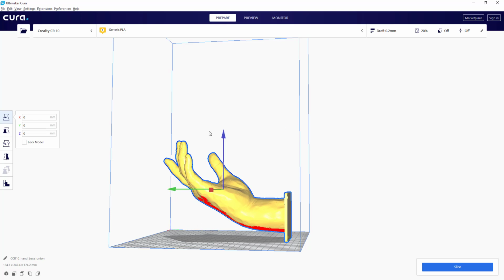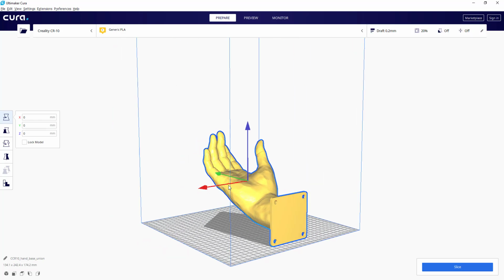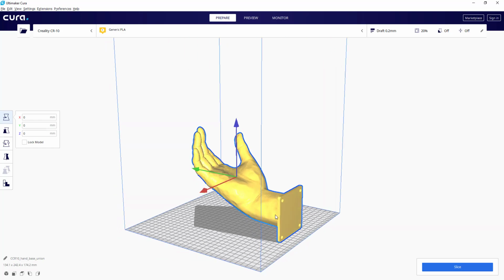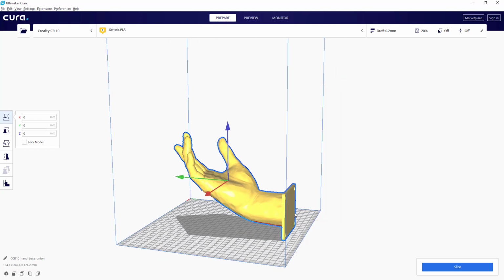The distance between each layer will be 0.2 millimeters. This model will not be completely solid, but it will be a 20% solid. This means in its inside it will only be a 20% filled. It will be hollowed in its other 80%.